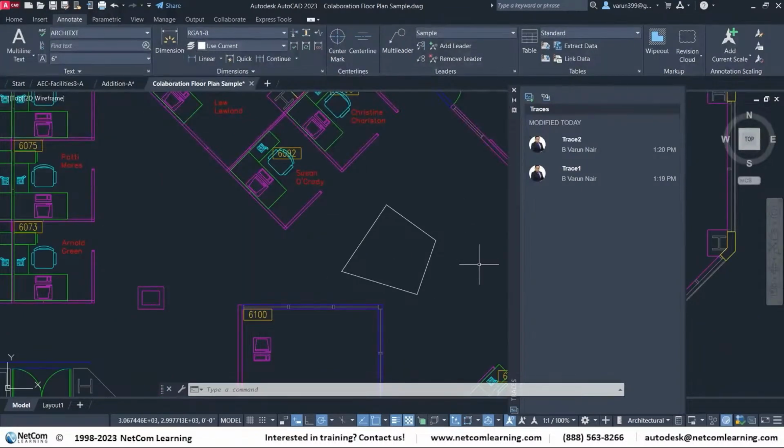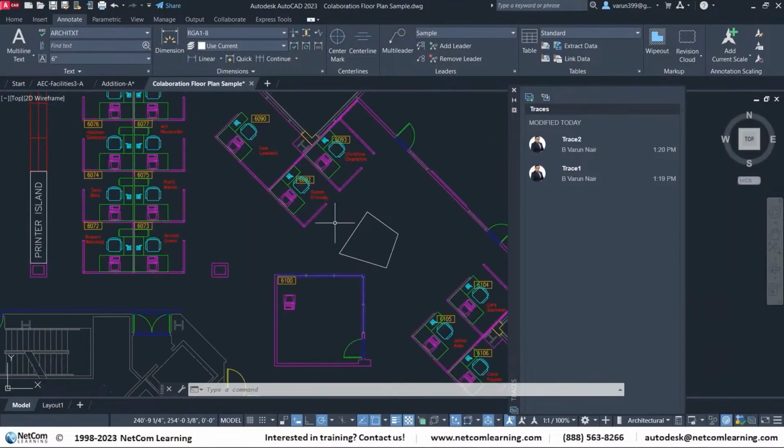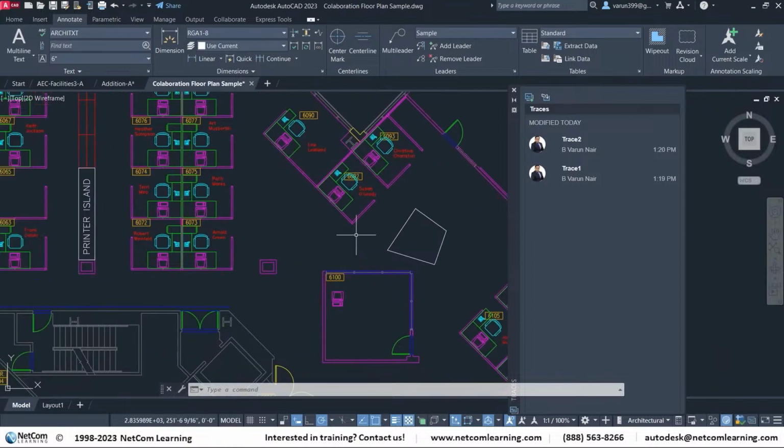Elias would like to know, how can we increase the size of text and arrow while creating a multi-leader? Yeah, it happens that when we create one revision cloud and try to incorporate some multi-leader into the drawing, it's pretty difficult to match the size of the multi-leader with the drawing. At times, the text size or the arrow size of that particular multi-leader may be very small or very huge. So in that scenario, we need to step down or step up the size of each text as well as the arrow that is being included in that multi-leader.